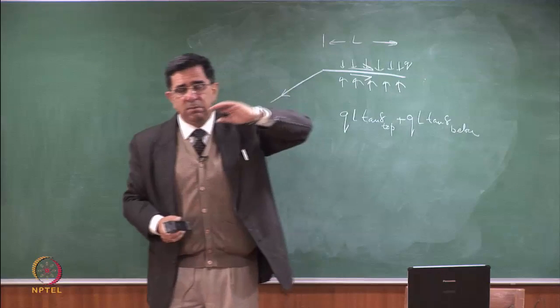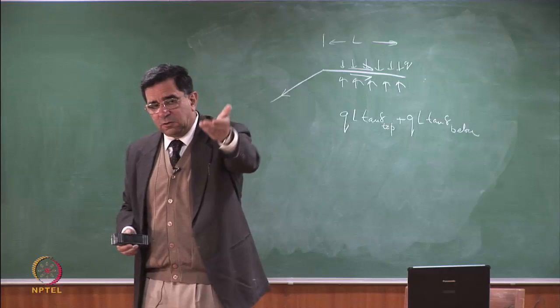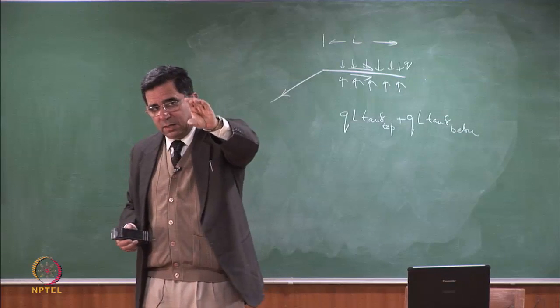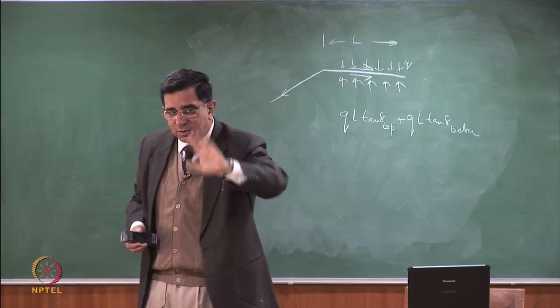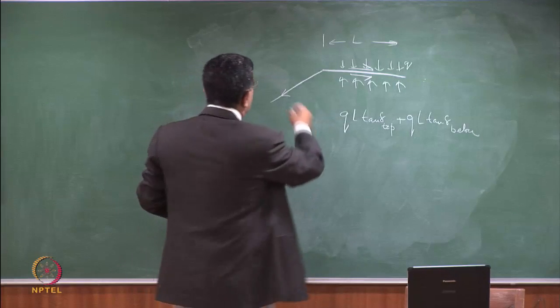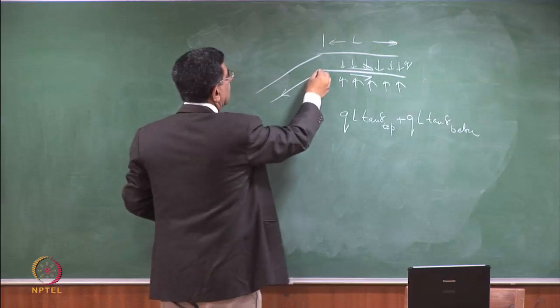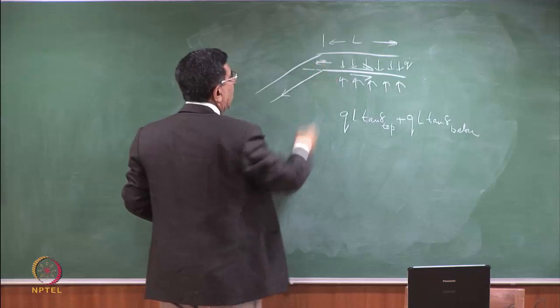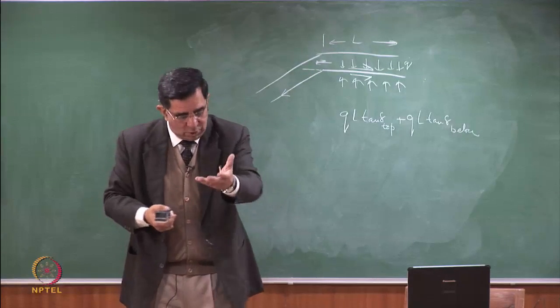But when your cover goes up, it is possible that when you pull the geomembrane, the cover will also come out, because it's not very thick, it's not restrained in position. So maybe this will move out along with the geomembrane. You put some soil on a geomembrane and try and pull it, the top soil can come with it.